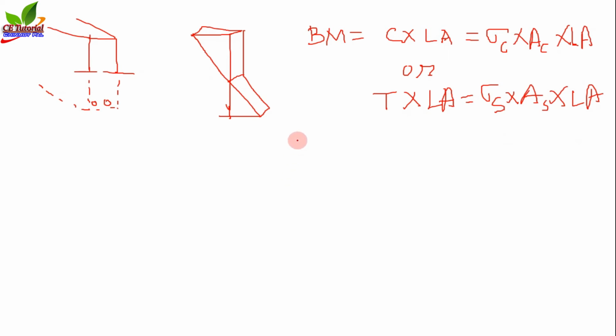Now you need to calculate C or T, because you have a three-dimensional bending stress diagram, and if you calculate the total volume of this three-dimensional figure, you can calculate C. So now what is the problem? Suppose this is the compressive stress.